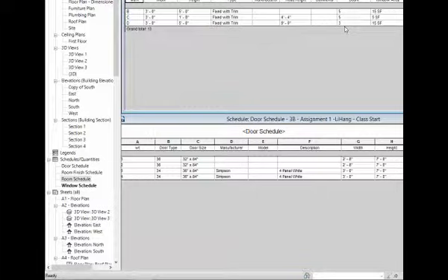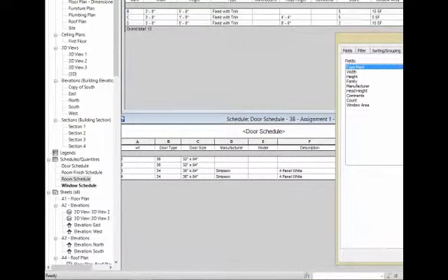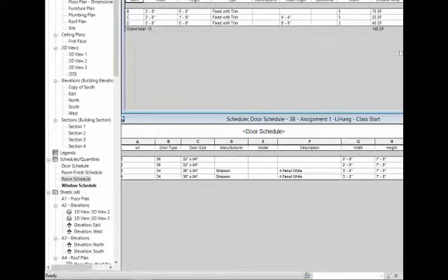So first we say we're going to add a total to that, and you say, hey, I put a total in there, but it's not showing up. What's wrong? Something's not working. Okay, and here's the last thing you need to do to make it work. We know you want totals, but you have to tell us which column you do want totaled, and that happens under the Formatting tab. So I can choose, let me total up that window area, say calculate a total on that, and then it will go through and calculate the total.